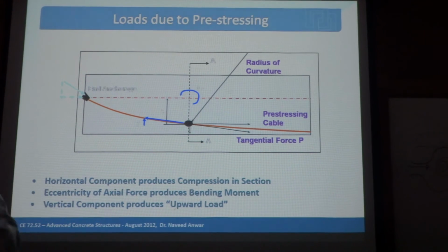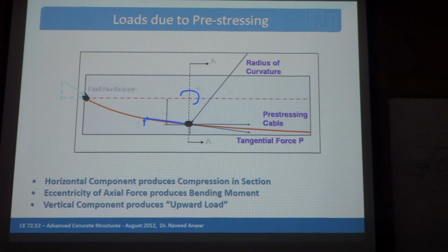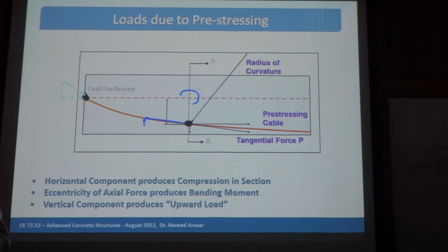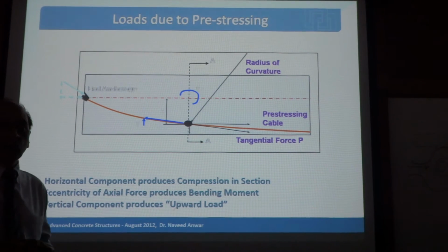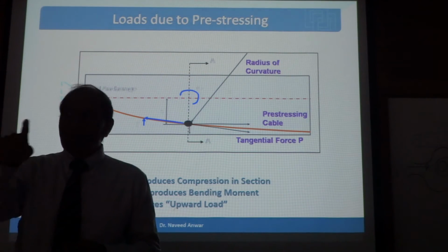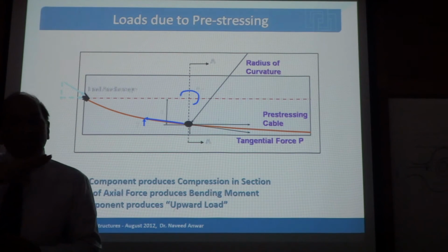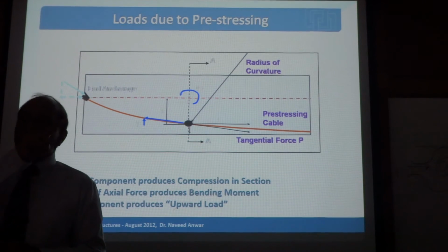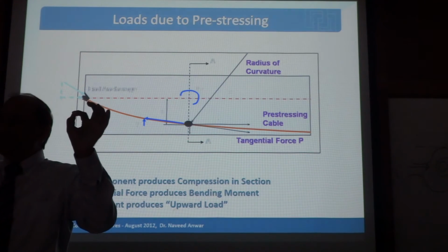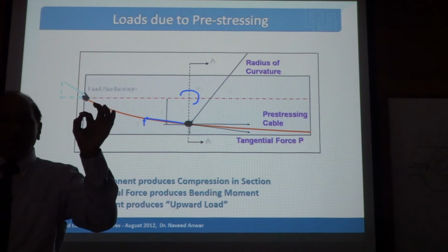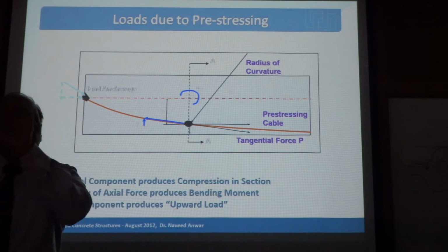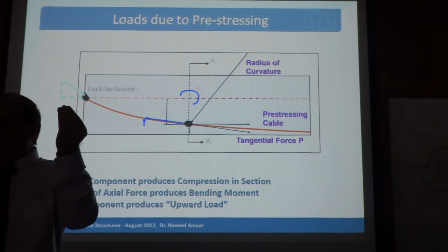Suppose there was no beam in that location and still you hang a certain cable, right, with a certain profile. That cable has a capacity to carry the loading because of its geometry, because it has inclined forces and the tension there. If you put the cable straight, it has no capacity to carry load, correct? If you just put the cable straight, you cannot put load on it.